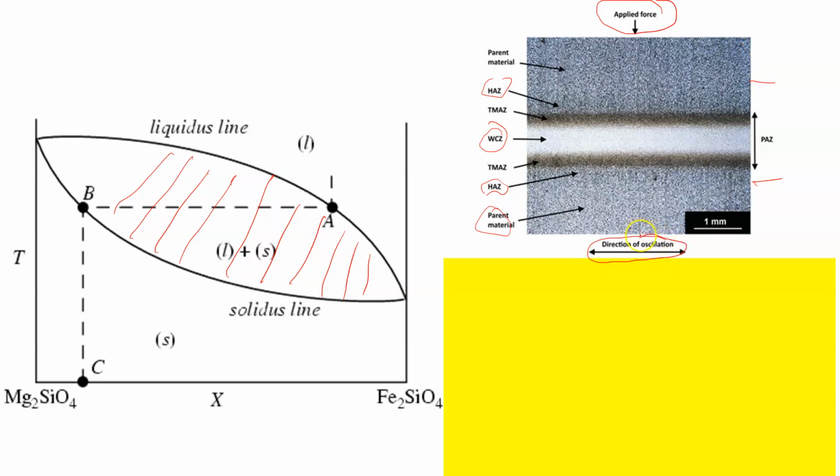And there's different types of solid state processes that depend totally on friction. So you apply a force, bring in some sort of relative motion. And in some cases, or a lot of cases, you might have an outside heat source, you know, an electrical current or some sort of electrical resistance or some other type of heat source. And that's what brings you to your bond. But at no point in time does it go to a molten state.